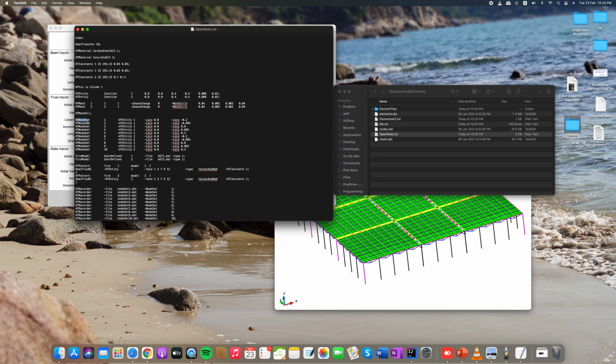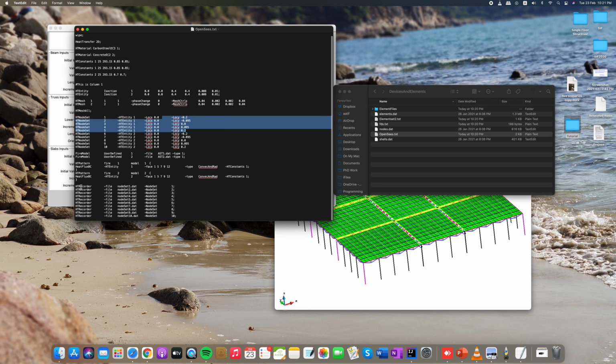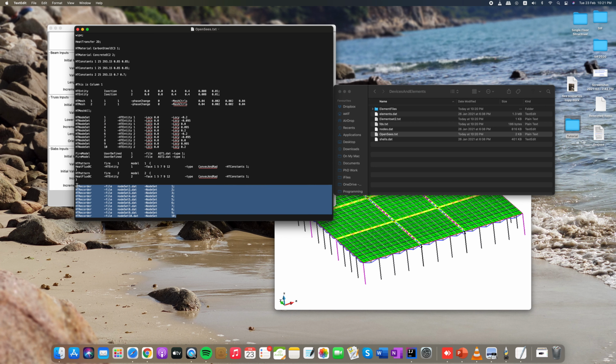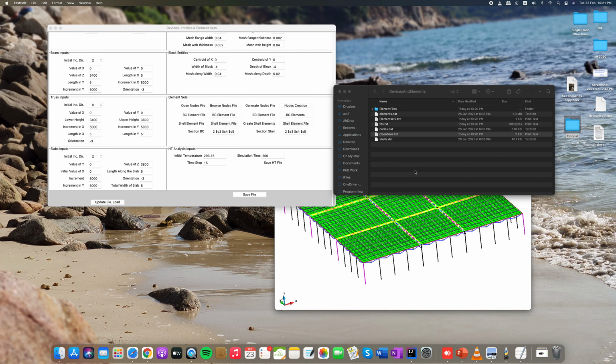It creates the node set. Because I want 5 locations, for each entity it is creating 5 nodes at -d/2, plus d/2, and so on, because the centroid is at 0, 0. Then the recorder means it will create 10 files for 2 entities for 1 column. I gave this comment also, so that when you are debugging or have any problems in your results, you can see where the problem is. I just gave this comment so that you can know which column is which. So this is how it is done.